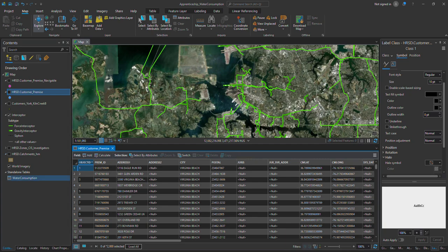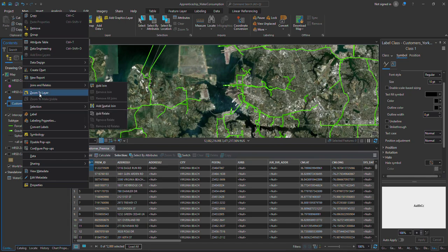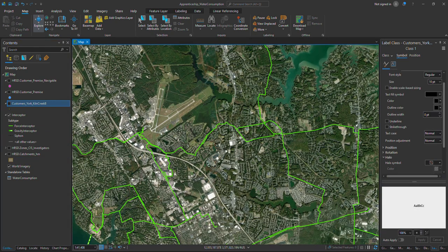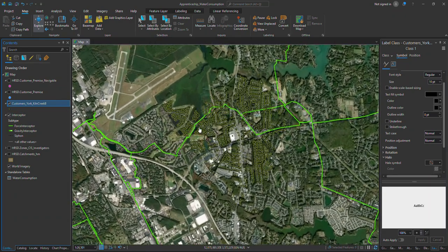So now we'll go through a spatial analysis exercise using this data. We're going to calculate water consumption for a specific catchment, and we need to find the daily flow to support a possible new connection to our system. So let's navigate to the area of interest and then check out the data we are working with. So here we have moved to the Kiln Creek area. In some of our data, we have a selection of customers here in these points,